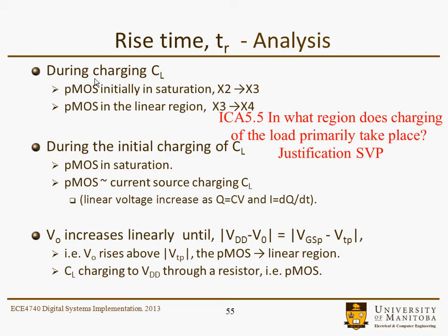So during the charging of CL, well, we already said that. Anyway, it brings us to in-class assignment 5.5. In what region does the charging of the load primarily take place? And some justification for that is going to be required. And I think what you'll find out is that the way that the figures are drawn are not all that accurate, and you maybe expect a little bit more of the charging in one or two of those regimes, and perhaps not the one that you might expect.